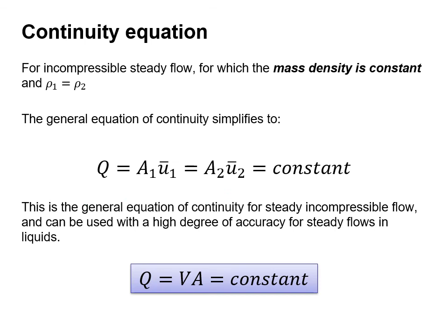For incompressible steady flow, for which the mass density is constant, the general equation of continuity can be simplified further. And this is the general equation of continuity for steady incompressible flow, and can be used with a high degree of accuracy for steady flows in liquids.